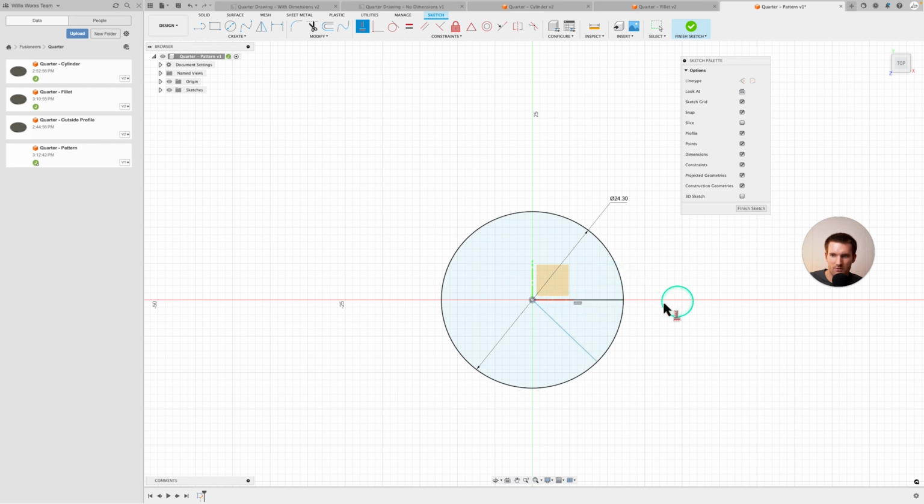So click, and now you'll see it's horizontal, and you see that little icon, which means that it is horizontally constrained. But we still have this one, which is not constrained. So the way that I would constrain this, actually we have a couple different options depending on how many slices of pizza we want, but I think let's go ahead and try horizontal vertical again. And so it actually made it horizontal because it was more horizontal than it was vertical. So let's click undo, so Command Z, click Command Z again. Now we have this, and now we don't have any operations selected, so we can click and drag and make it go a little bit more vertical, and you can see how it'll kind of snap, but that's not fully constraining it yet.